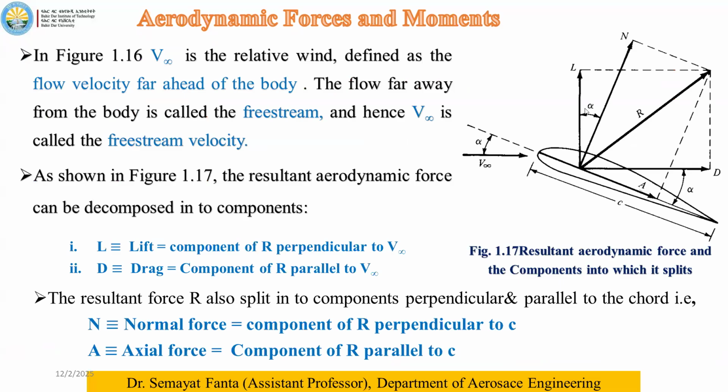So look, we have lift in this direction and drag in this direction. The drag force is in the direction of flow velocity or stream velocity. The lift is perpendicular to the drag. And then we can also resolve this resultant force into the normal force, perpendicular to the chord, and the axial force along the chord. Here, two different force representations are there.